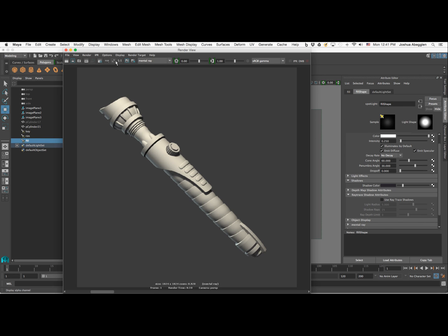All right, this render is done. Let's go ahead and save that so I can scrub back and forth between having the intensity of 1 and the intensity of 0.25. So that does look a lot better. I'm going to click on this icon and delete the intensity of 1 and compare it to without the fill light and with the fill light. All right, and you can see how it's kind of pumping that neutral light into everything, including the halftone and the highlight, and especially in that core shadow. And I still think it's just a little too intense. So I'll go ahead and maybe set this at a 0.1 and go from there.